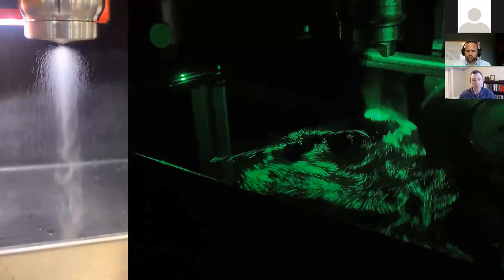And once you have an idea of the transfer efficiency, the percentage of sprayed material that reaches and stays with your target, then you can start to, again, go back to what is my overall flow rate, what's my conveyor speed, and calculate how much material will be landing across a given area or surface.